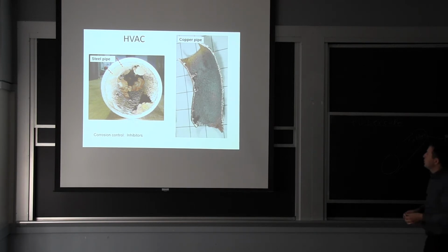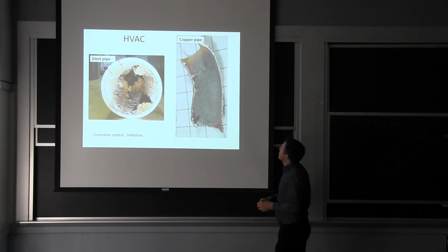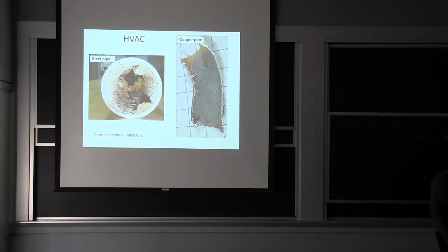I have that example here. This is the copper pipe, and you probably can see on the image, if you look at that bend right here, it's a completely different project, but you can see it's pretty thin wall, even though it's not polished, but it's much thinner than on the inside of the curve. So that's a situation where the copper pipe was not being protected, passivated, because of the local flow of the circulating fluid.